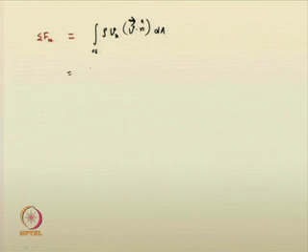What is sigma f x? Sigma f x is nothing but the steady state condition. Okay. So, rho into V x, then V dot n vectorial, so V dot n dA. For this particular vane, you know what this quantity is in the x direction at the outlet: V 0 minus u.